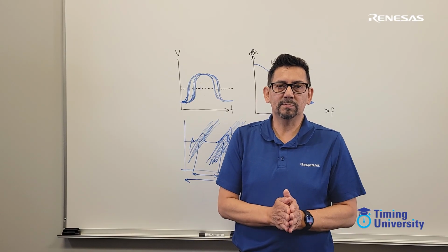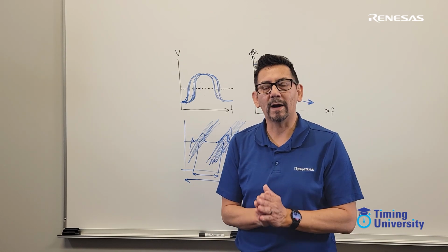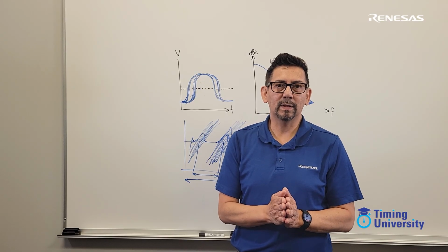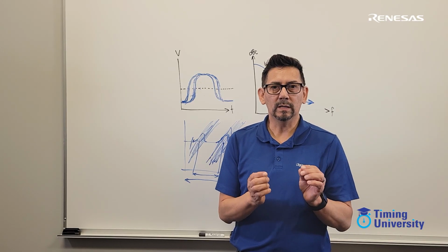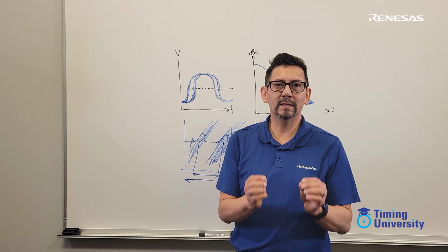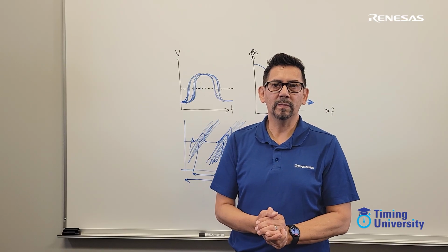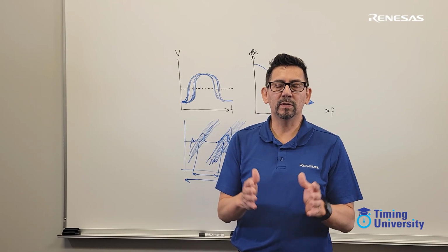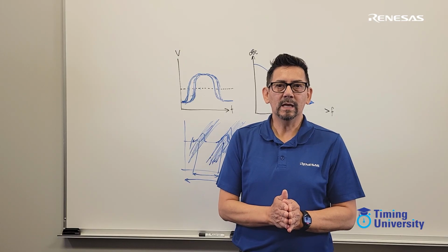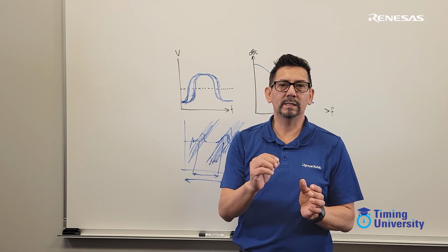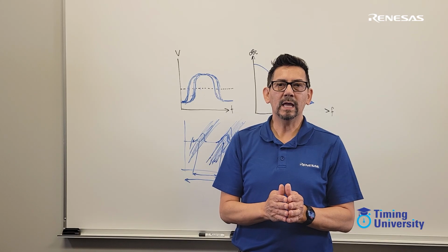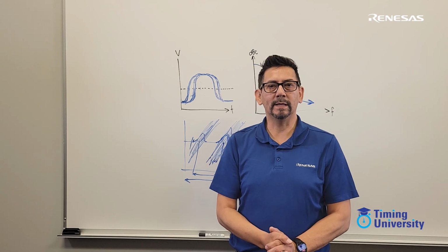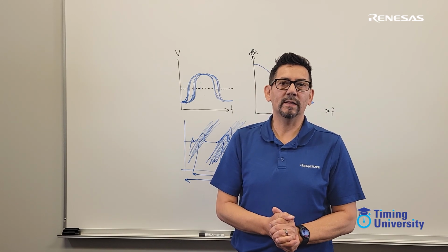Now, if you still see the spur, then most likely it's coming from the power supply. In that case, what I would do is turn off the power supply and use an external lab power supply to provide clean power to the chip. At that point, you should be getting a clean signal. Then I would power up the rest of the board and see if perhaps that power supply was the cause of the noise. So let's say it was the cause of the noise, then you can focus on the power filtering or maybe consider an LDO to help reject that noise.